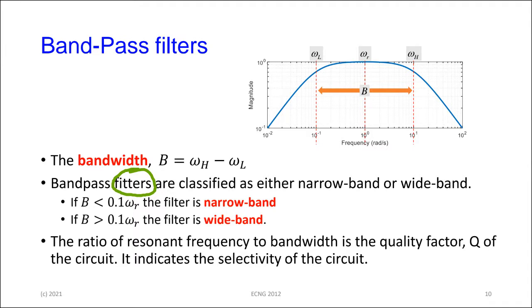So for instance, an amplifier will be a wideband filter; the behavior is like a wideband filter. Narrowband filters would be the ones used, for instance, in radio circuits. So tuning, as we spoke before elsewhere, when you tune to a particular frequency to listen to it, the filter in the electronics that is locking on to that frequency is going to be a very narrow band filter.